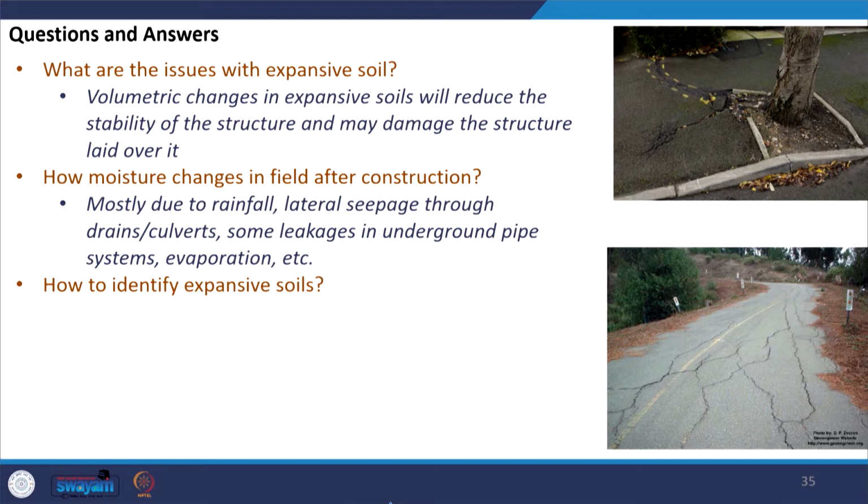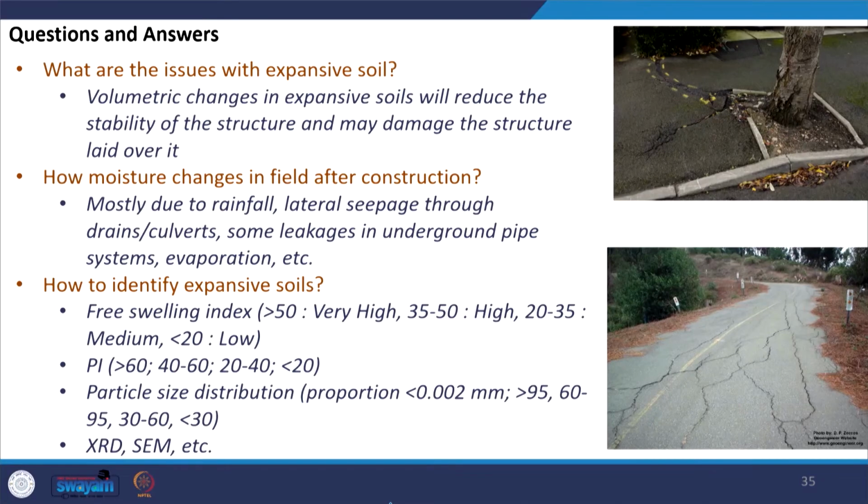So, of course, in this direction there are various tests that are available. You can take the soil, you can go to the lab and do some set of testing, and the properties or the values after the testing will tell us whether the soil is expansive or not. Okay. Various laboratory tests have been proposed. These are some of the common or popular tests that are usually used for identification of the expansive soil. The most common test being the free swelling index.